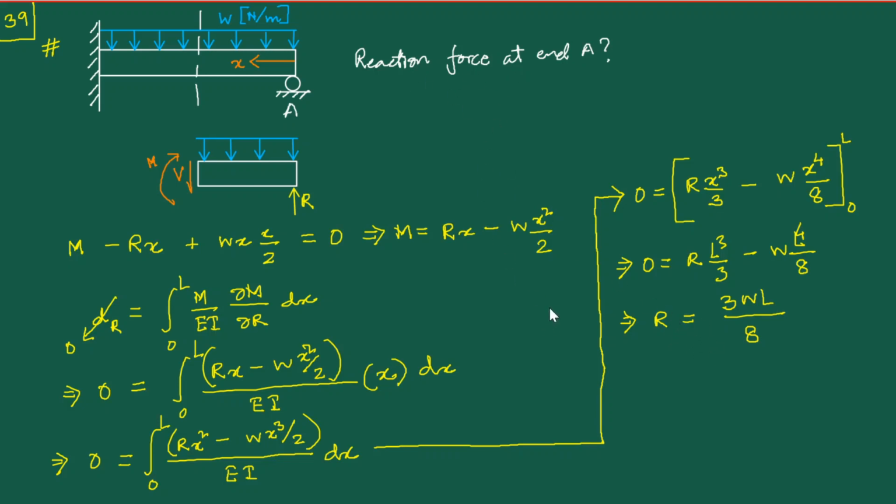Now regarding the danger that I was alluding to earlier, please note that this entire method works for statically indeterminate problems. It is not going to work for statically determinate problems. We'll discuss this after the next example, but let me just write it as a fair warning here, maybe with the red sign and the skull symbol.